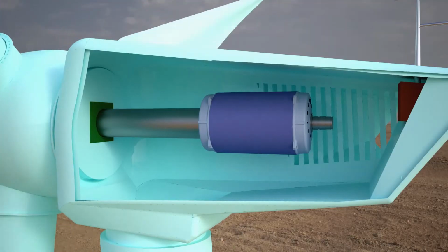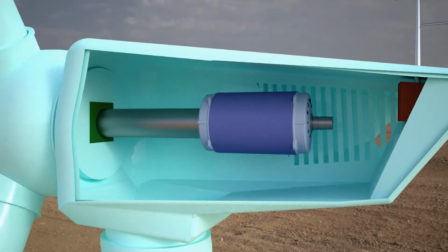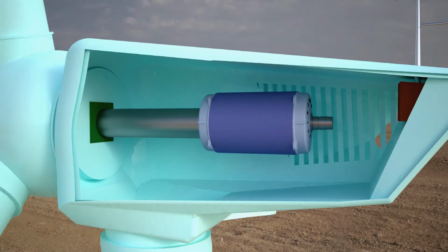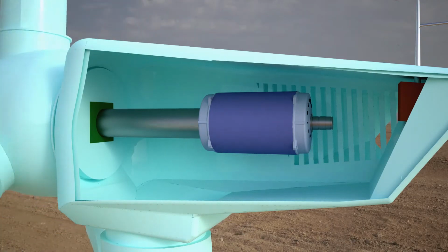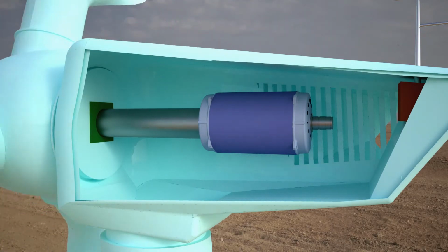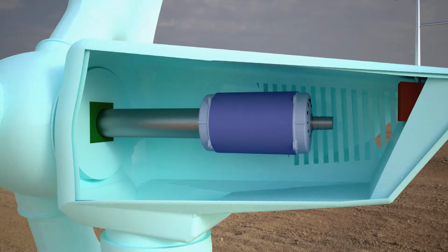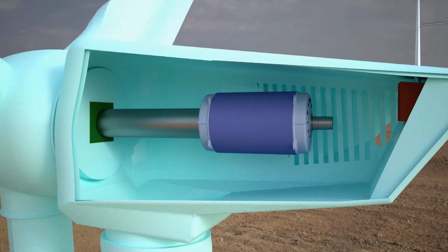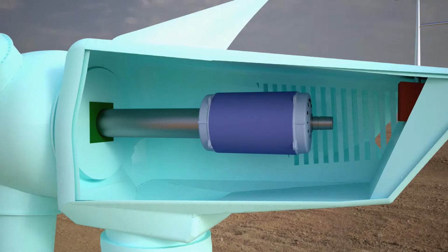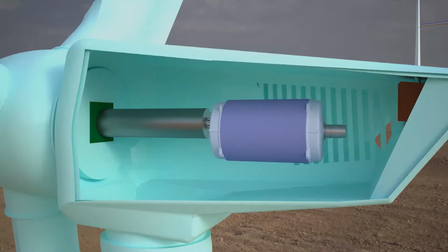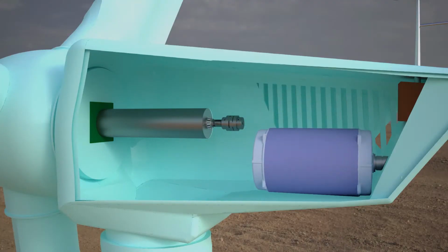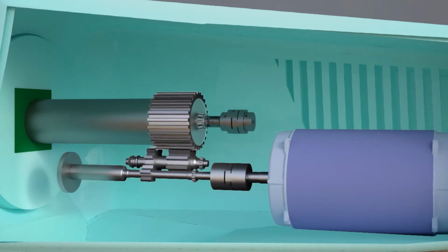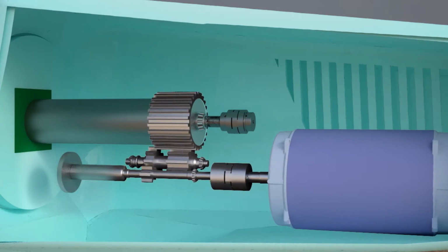The wind turbine blades typically turn at a very low rate of RPM due to the issues of noise and mechanical strength. At this level of rotation we cannot produce any meaningful electricity from a generator. We have to increase the speed of the rotation of the generator. So this setup uses a planetary gearbox to achieve the maximum speed. If the wind is blowing at high speed, the turbine may be damaged. So the brake system is placed to control the overspeed on windy days.